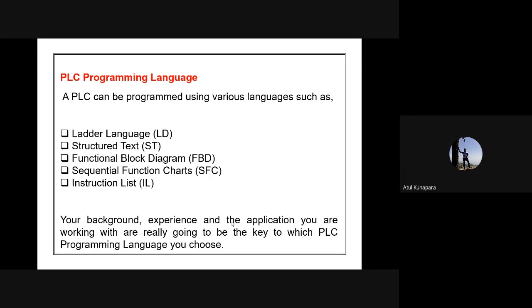And it is not the case that ladder language is feasible everywhere or in all automation parts. It depends on your particular background. For example, if you are good with C programming, then structured text is a good language for you to use in your PLC. So depending on your background, your experience, and the application where you are working, which language is preferable is going to change. But in most applications, ladder language is suitable, and that's why most industries are working with ladder language.